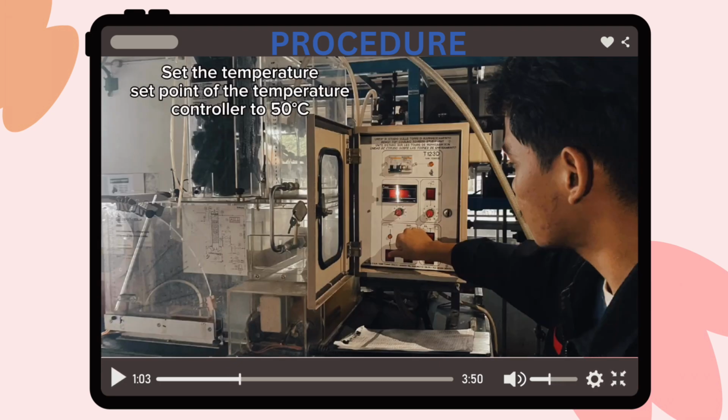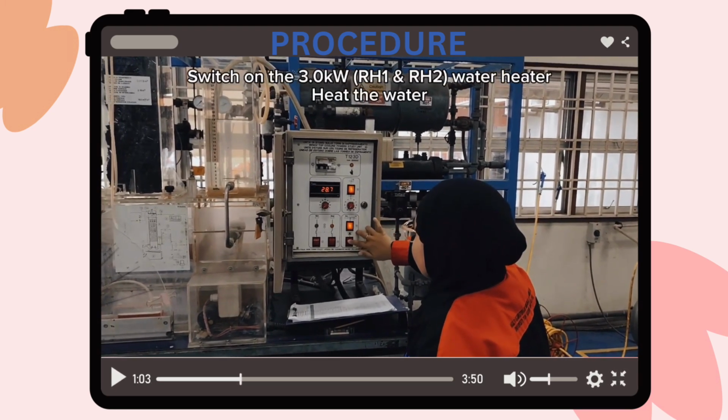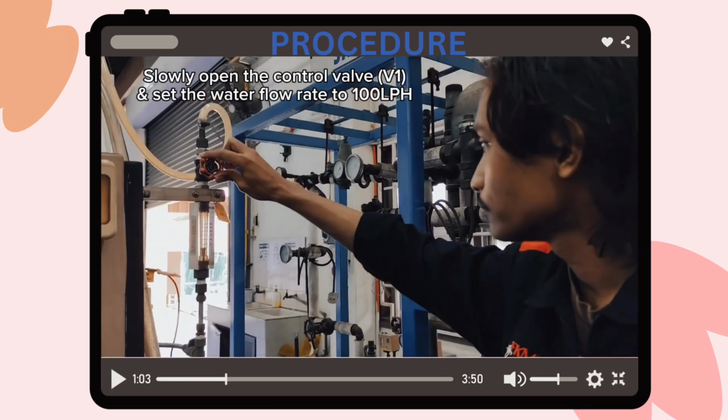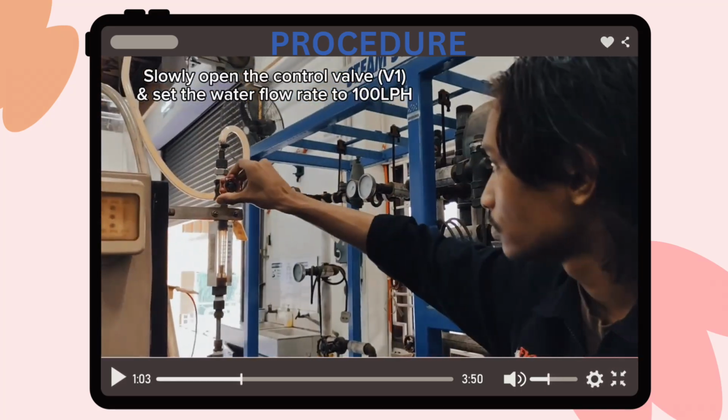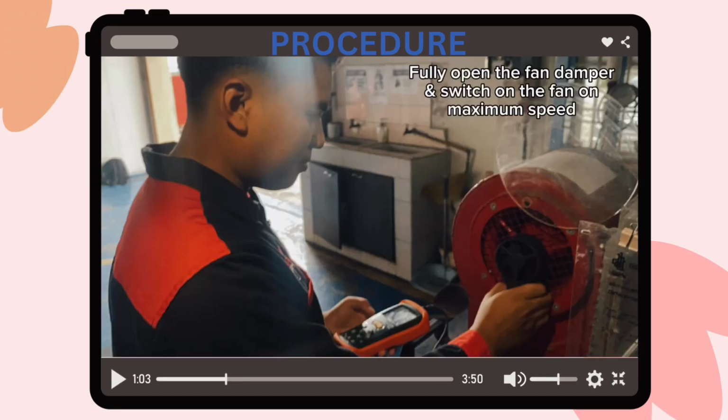Set the temperature set point of the temperature controller to 50 degrees Celsius. Switch on the 3 kW water heater. Heat the water. Switch on the pump. Slowly open the control valve and set the water flow rate to 100 lph. Fully open the fan damper and switch on the fan at maximum speed.